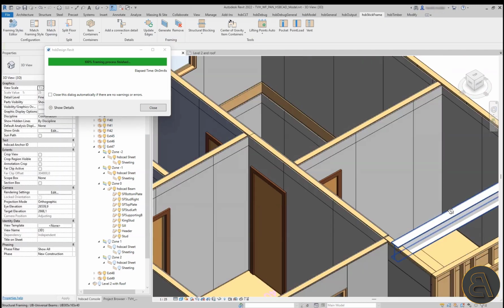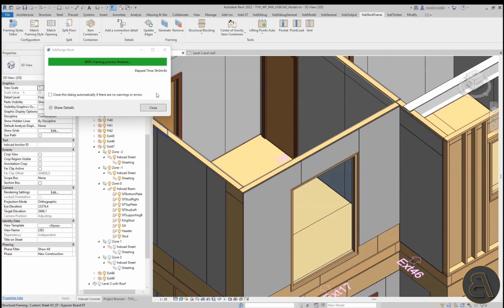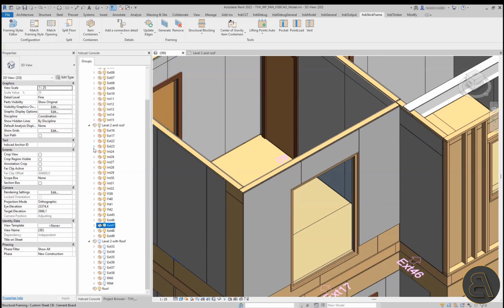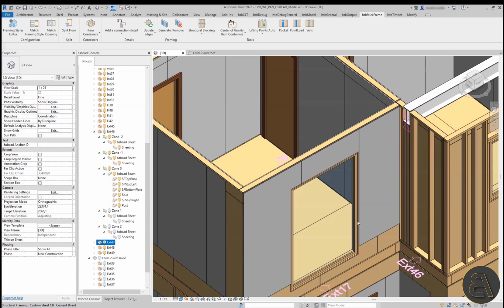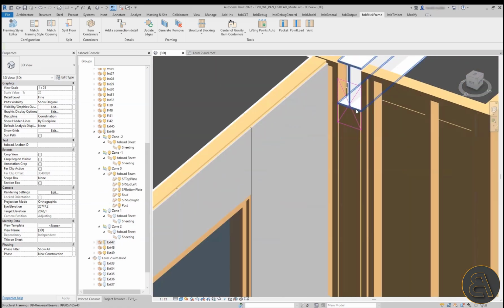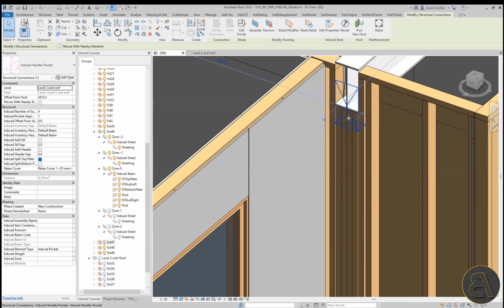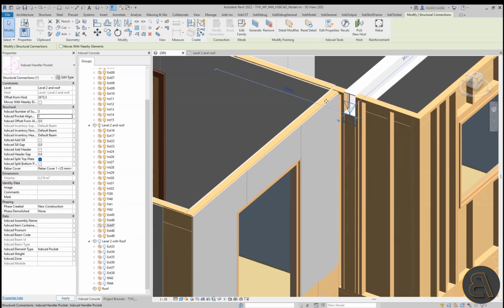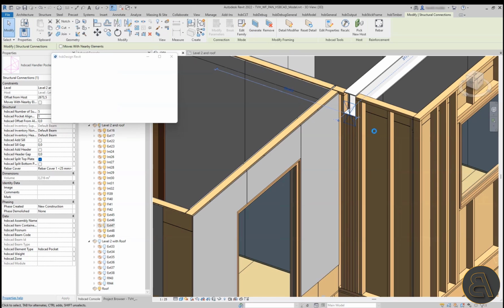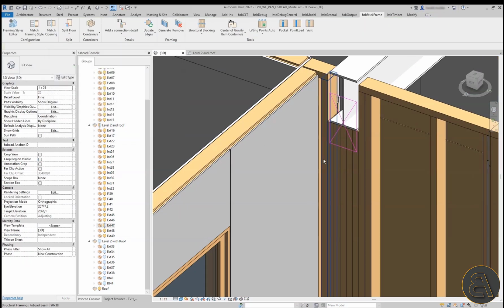Then I'm going to view exterior 46. Then I'm going to turn off my zone 1 and zone 2. There we go. We have our extra beam below. Once you change that, let's say from 4 to, for example, 5, from the select tool up here, change it to 5 and frame my wall. There's our result. Now we have 5.